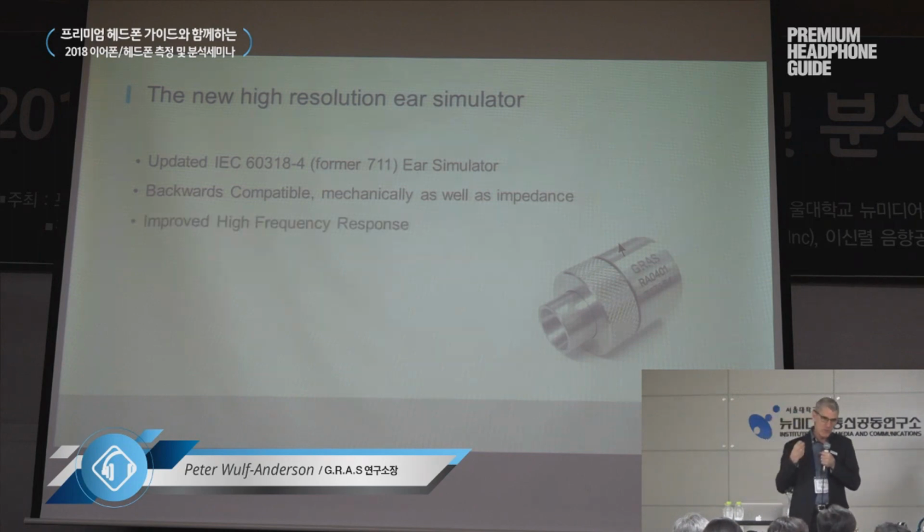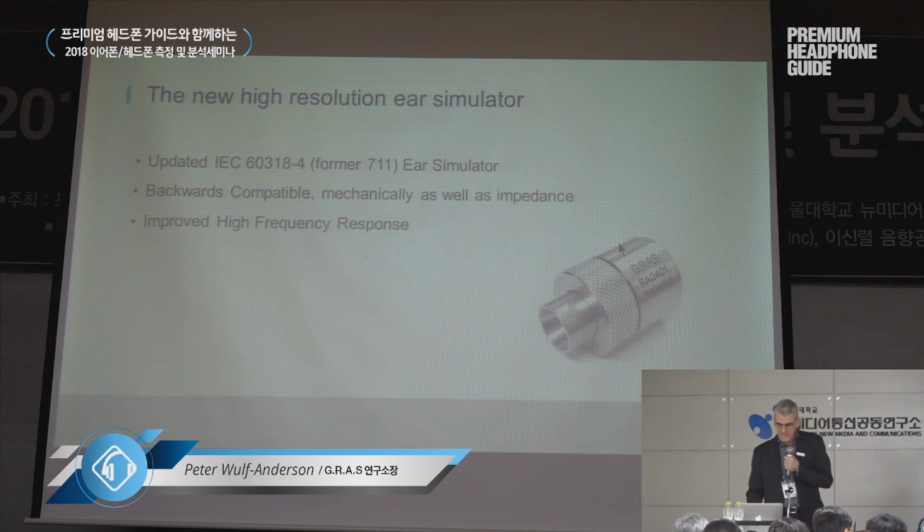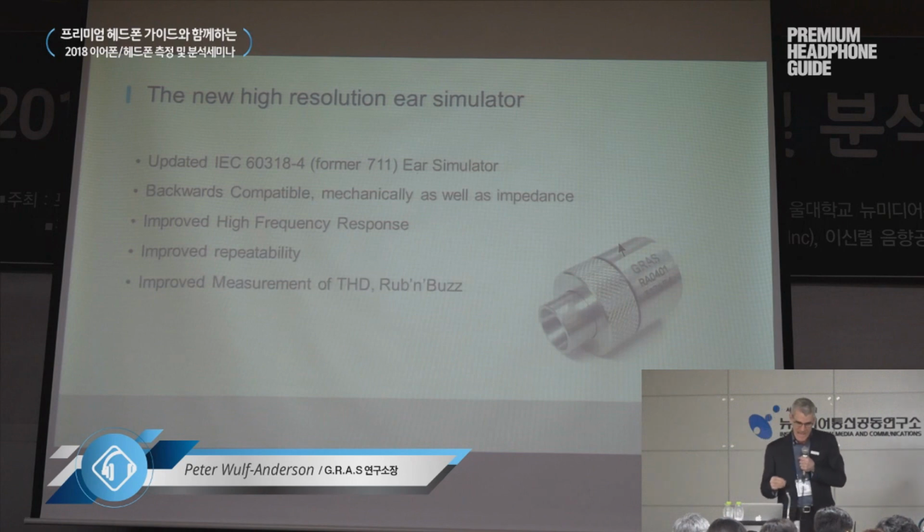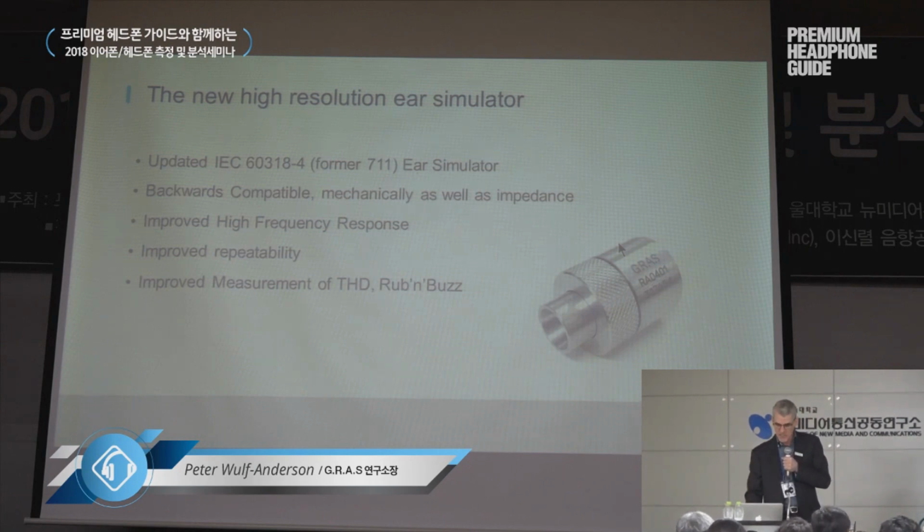But we wanted to improve the high frequency response, so we didn't have to fight with all these sharp resonances. By doing that, it would give you a much more repeatable result up at high frequencies. And as a little side effect, which I will explain more in detail later, it also improved the measurement of THD and Rub & Buzz.